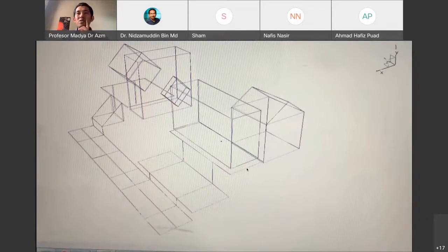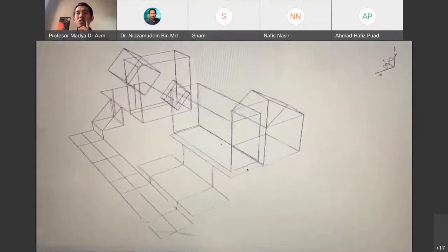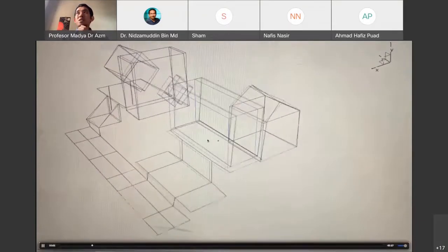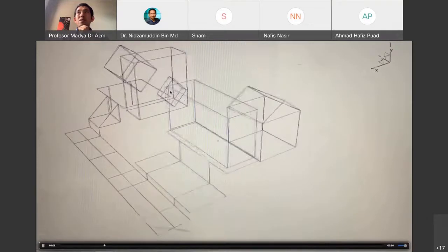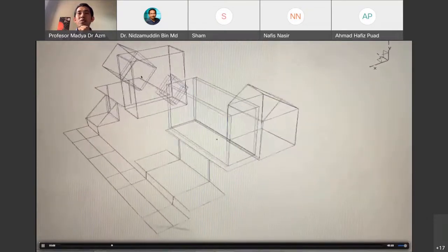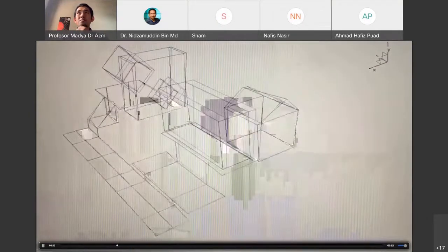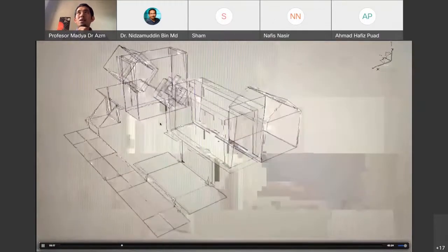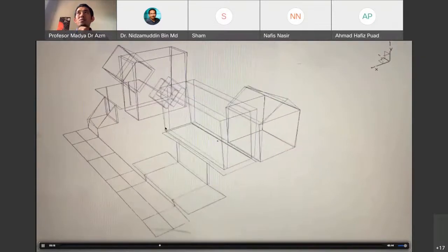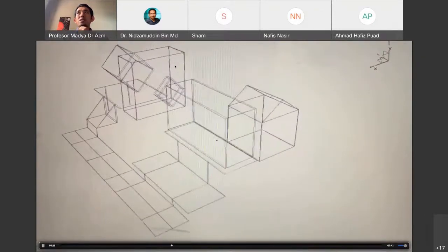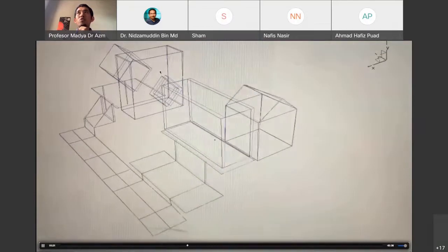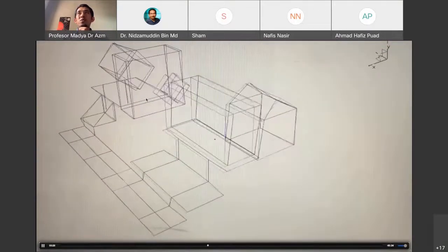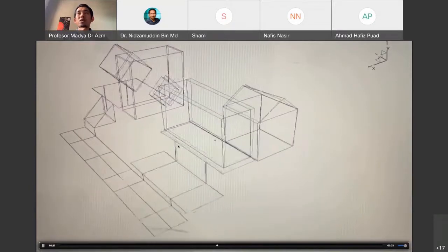Okay, so this is the simulation of the vibrations. This is the gearbox, and the opposite one is the motor. If you look closely, the gearbox is somewhat 185 degrees from the motor, so something is not right with the coupling.